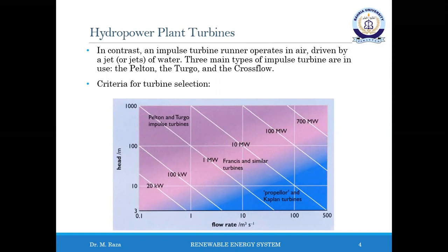Turbine choice is based on the principal site characteristics, that is, available head and flow including flow variation, that is, if the turbine operates in part load condition. For example, when available discharge throughout the year is typically lower than the turbine design discharge.